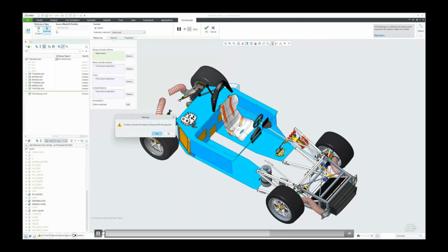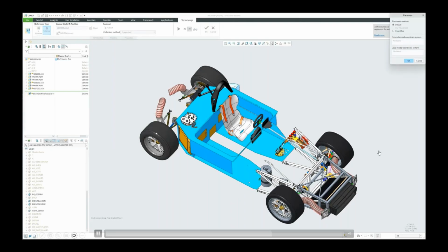What I now want to do is talk through shrink wraps. So I'm working on this chassis, and I probably would have done this at the start, but it doesn't really matter. I want to understand how my chassis is going to work with the design team that's working on the transmission. So I want to have a representation of the transmission in my chassis here that I can work around as a bit of a space claim. I don't want to bring that data into my model. It's going to bog me down. It's just going to lock up the users that are trying to work on the transmission if I've got that data in session. So what I'm actually going to do is create a shrink wrap of the transmission.